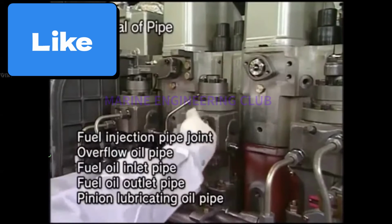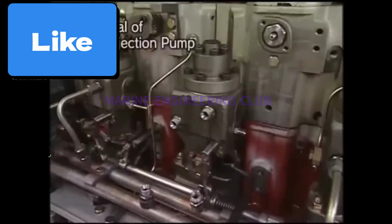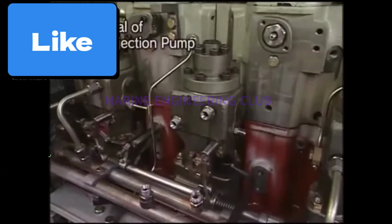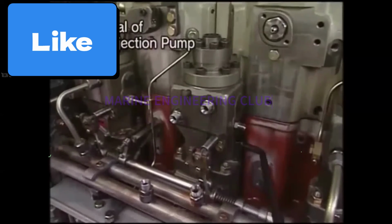So you will remove all pipeline connections. Now before removing the bolts, obviously you have to disconnect your rack from your regulating shaft. Your pipelines have to be disconnected, the high pressure pipeline has to be disconnected. Before opening up these 4 foundation bolts, make sure that your pump plunger is at BDC. I have given you the reason for it. Otherwise it will jump off. So now you open it up.